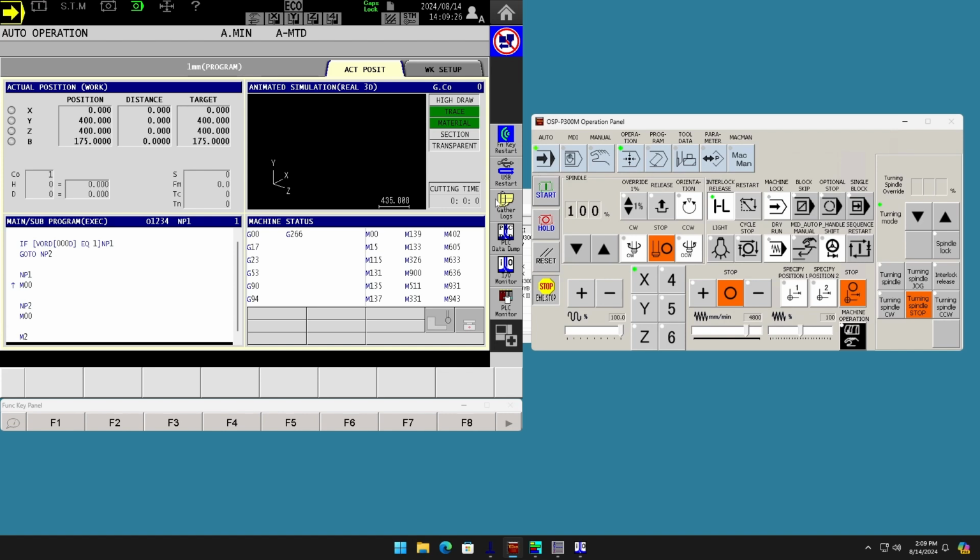It would set the tool count back to 0, or basically if it could run 100 parts, it would set it back to 100 so that it was a fresh tool. And then it would also touch that tool off and put it away. So this allowed operators to kind of step through more quickly on their tool management systems and not even have to really think too hard about it.